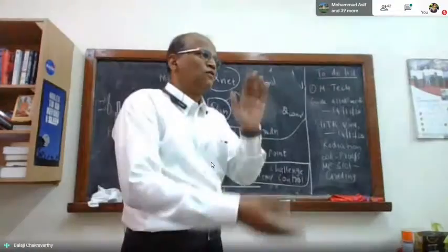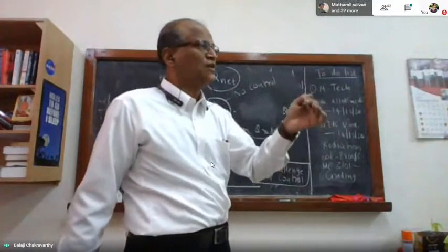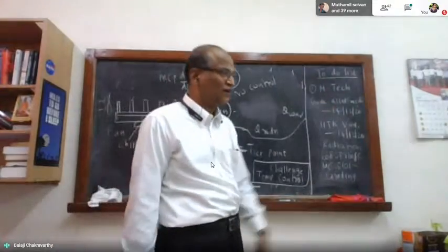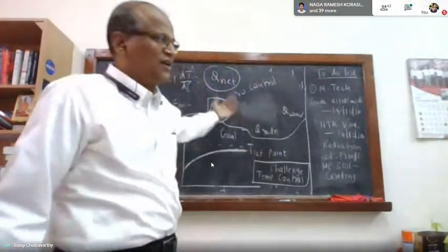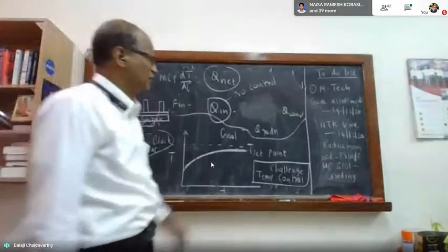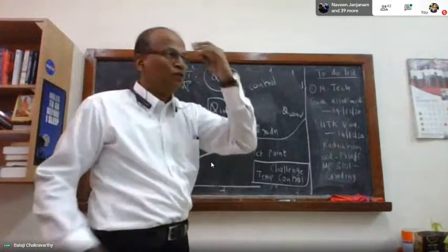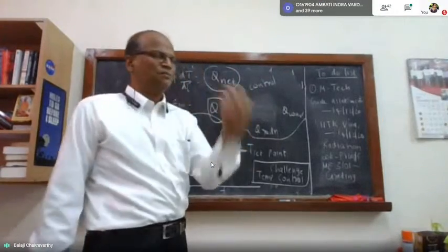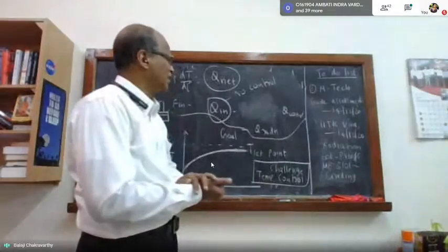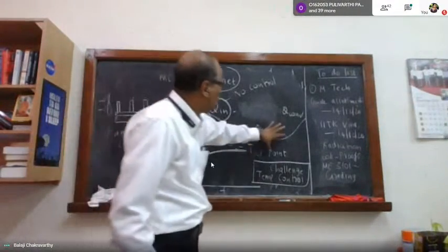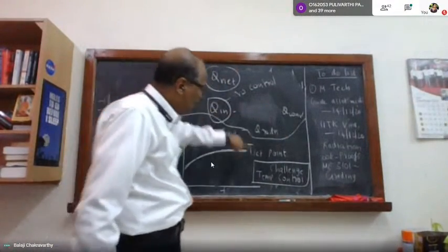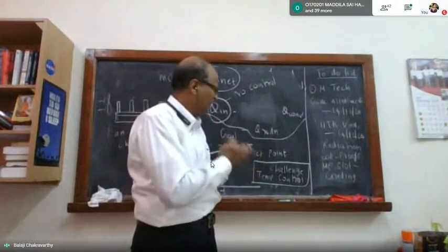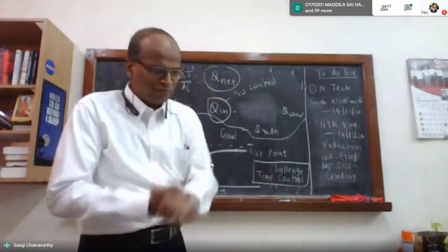Whereas a heat transfer teacher would have told you that the basic idea of studying heat transfer is to understand the processes and be able to calculate the heat transfer, we go one step further in thermal control of electronic equipment. You understand heat transfer. Please know the mechanisms of heat transfer. Please have ways and means of finding out how to calculate the heat transfer. Don't stop there. Put all of them in an equation like this and try to find out the temperature, with the view that the challenge is to be able to control the temperature.